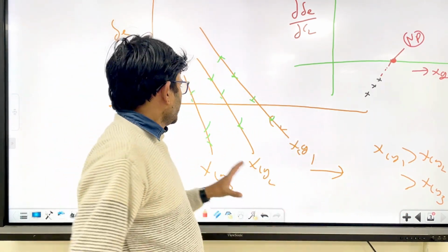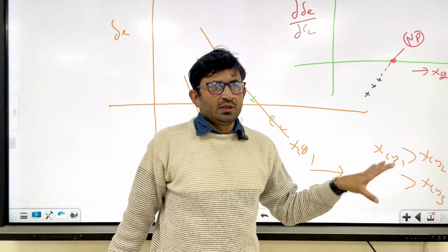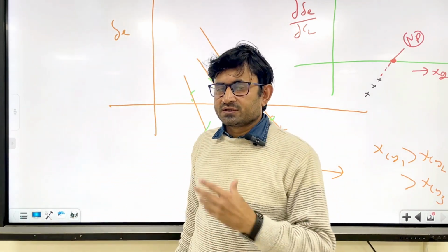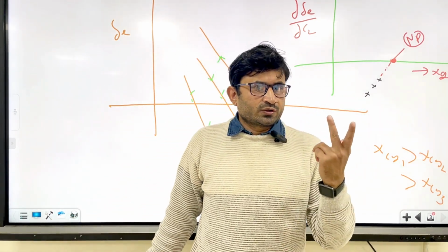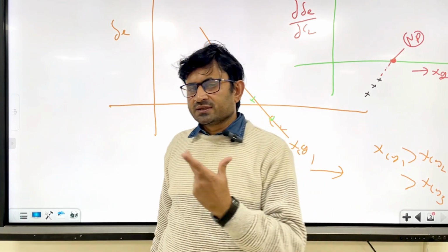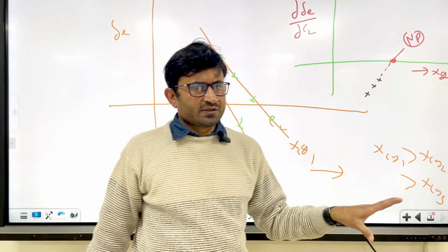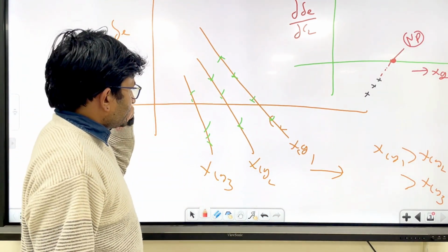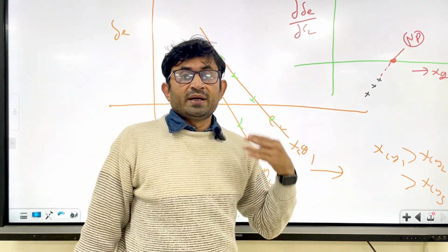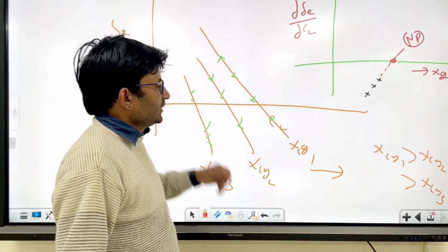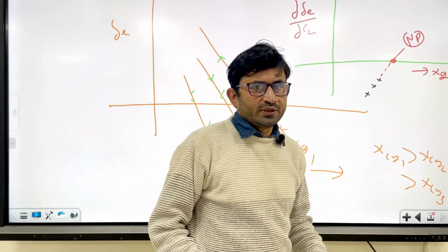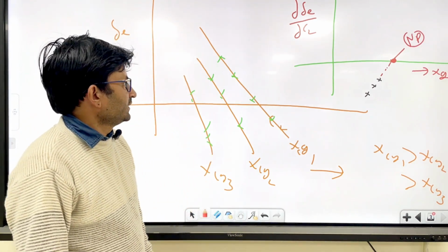And how will you get different CG? You can distribute the weight. Let's say if you are flying a 6-seater, you can go with the first 2 passengers, then 4 passengers, and then 6 passengers. So you can fly with different CG locations. At different velocities you have a different Cl, and in order to maintain that Cl, you have a different delta E. So all things are in your hand. That is how the neutral point is measured experimentally.